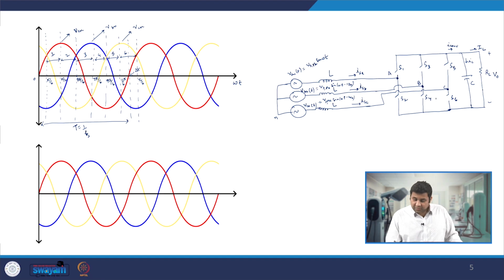So thus we must ensure that this one half bridge is actually modulated with the sine waves which are 120-degree away from each other. So let us define these as the modulating wave for phase A, VMA we can say, this is VMB, this is VMC. Modulating wave for phase A, for phase B, for phase C.